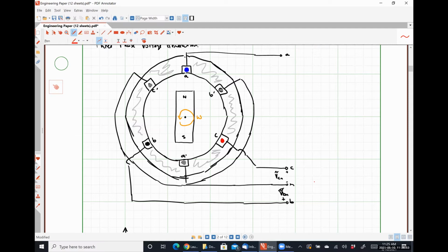So that's really the only difference between those two. You hook it up one way to make it spin clockwise, the other way to make it spin counterclockwise. One way has what's called a positive phase sequence, the other way has what's called a negative phase sequence. From a circuit analysis perspective, it's the exact same thing, except that all your angles will have plus signs instead of minus signs.